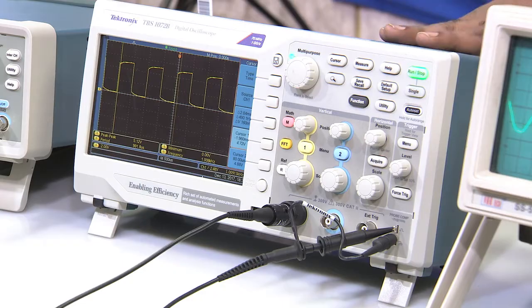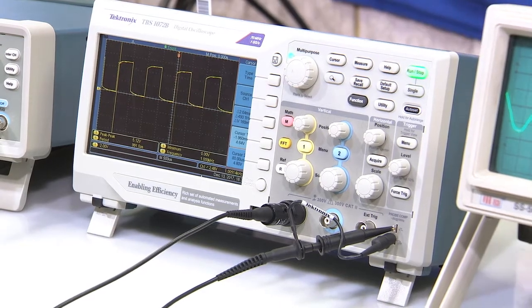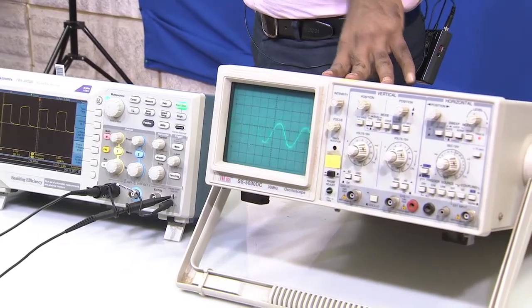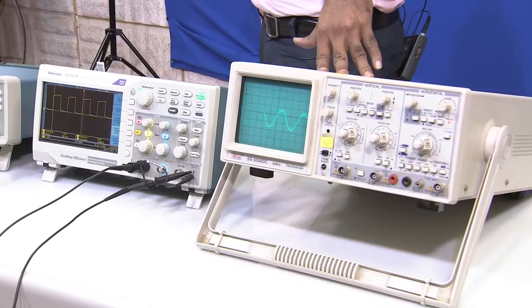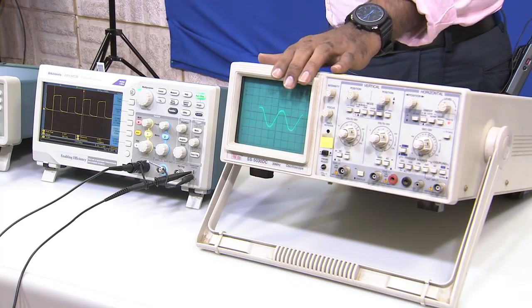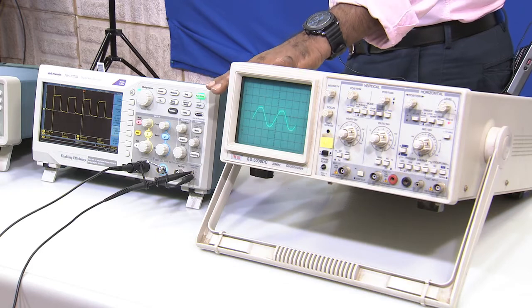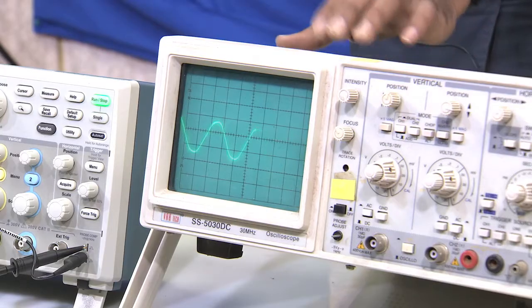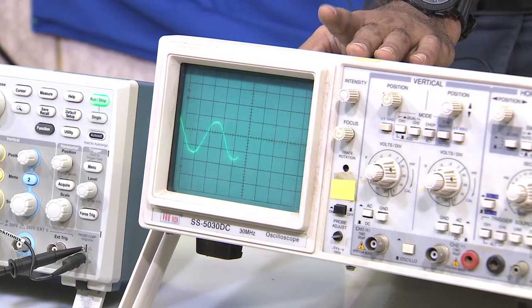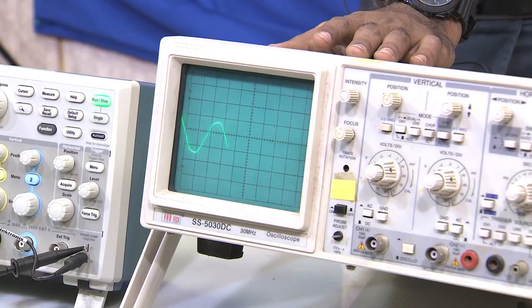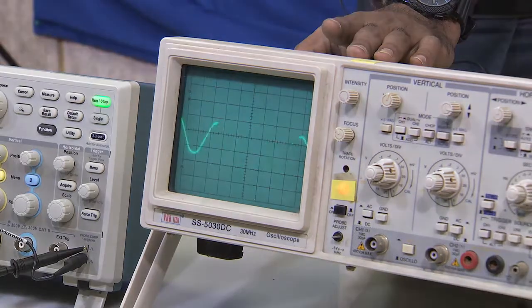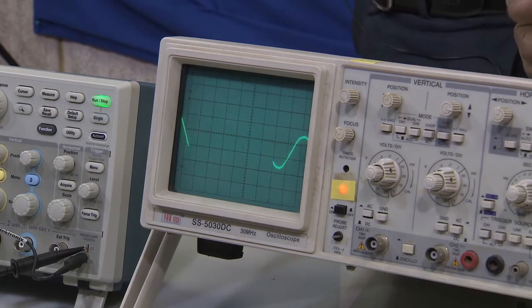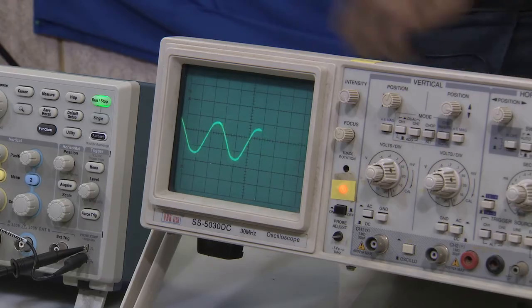Also, let us compare this digital oscilloscope with the CRO. Now this is your CRO oscilloscope, CRO meaning cathode ray oscilloscope. In this you can see similar functions, but in a more crude way, alright. So, let us see what the functions are. First is the intensity and focus, because in a digital oscilloscope we use either LCD or LED, while here we are using the cathode ray tube. So here we have to change the intensity and the focus. Can we please show the change in intensity?